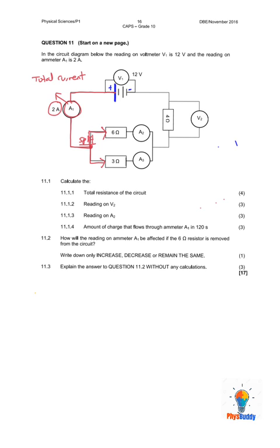If we continue this, we can see that ammeter A2 measures the current that comes out of the 6 ohm resistor, and ammeter A3 measures the current that comes out of the 3 ohm resistor. And then we can see that at this point, the current is back. The total current is now together again, and it is the total current that flows through the 4 ohm. So that tells us that the same 2 amperes, the total current, is what flows through the 4 ohm resistor, and then it returns back to the battery.